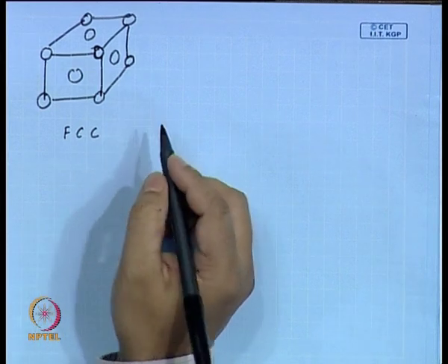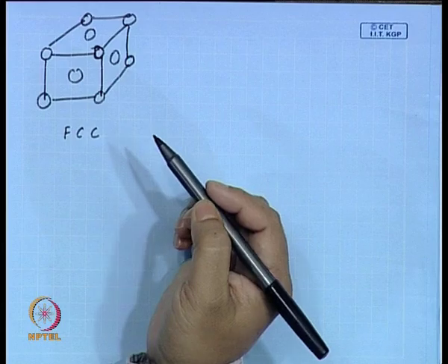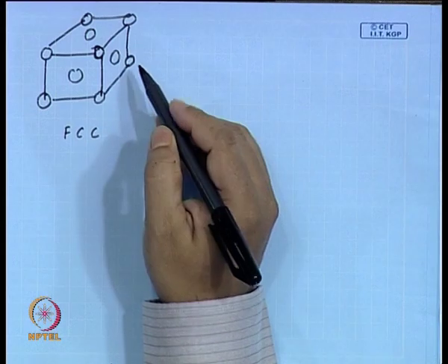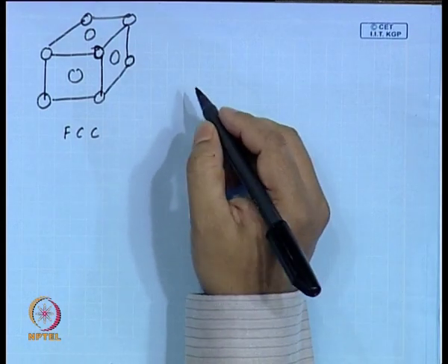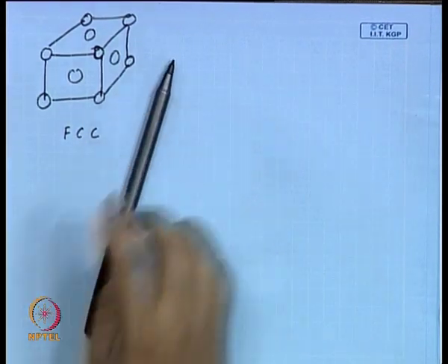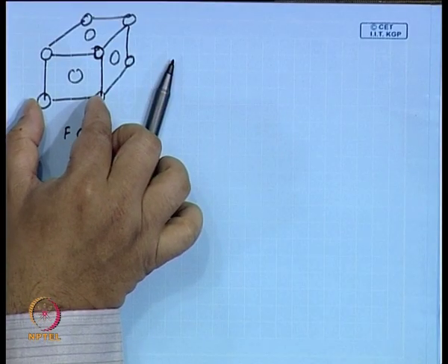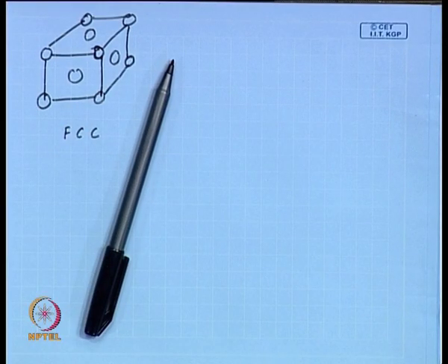Silicon is basically an interpenetrating network of face centered cubic lattice. Now, that is not the end of it. It is basically, think of two lattices placed one over the other. Think of two cubes placed one over the other. Okay. Then you shift one cube from the other by 1/4 distance. If 1 is the distance between the two atoms here, you go by 1/4 distance, shift 1/4 on x axis, shift 1/4 to y axis, shift 1/4 to z axis.